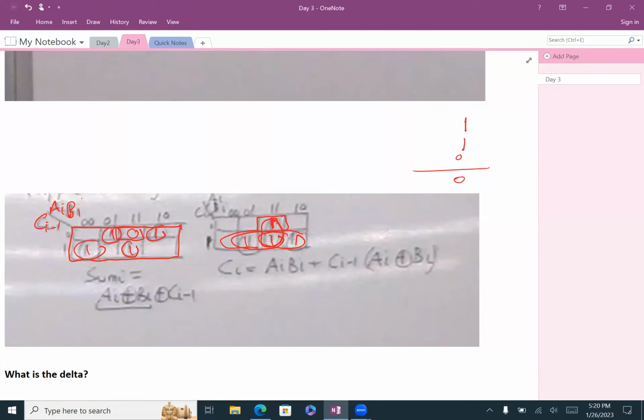All right. Now, what's the delta we said? 12. Perfect. And that's the issue. Why do we have the big delta? Because we are waiting on the carry. So the carry is holding us. So if there is a way to break the carry or find all these carries at the same time, you will save a lot of time.